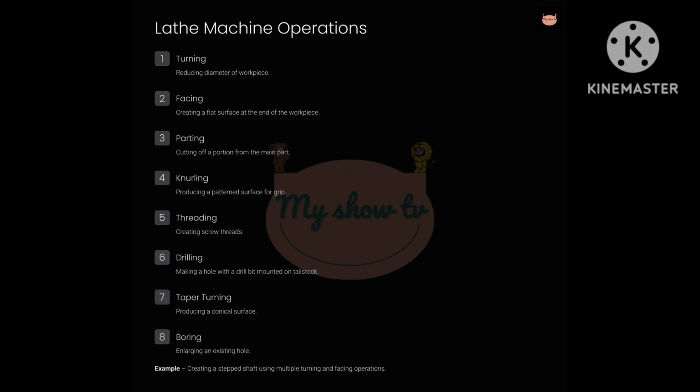Slide 3. Lathe machine operations. Let's go deeper into what a lathe can do. 1. Turning. This is the basic operation of reducing the outer diameter of a rotating workpiece. Think of reshaping a thick steel rod into a thinner one. 2. Facing. Cutting a flat surface at the end of a workpiece. 3. Parting, or cut off, used to cut off a section of the job. 4. Knurling, which creates patterned textures, diamond or straight lines, on handles or knobs to enhance grip.